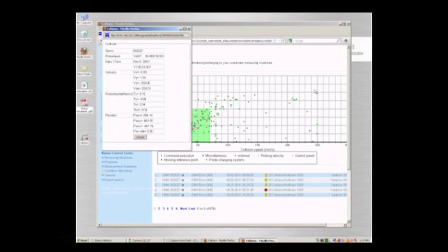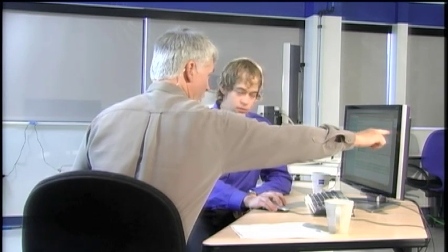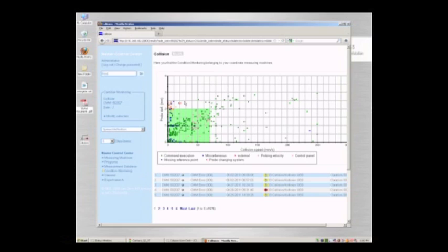What are we seeing here, the X and the Y axis? What we see here is actually a collision speed, so millimeters per second, on the x-axis. And then we see probe head or probe deflection, so how much did the probe actually bend. So the worst case would be really high speed, a whole lot of deflection. Exactly. Parts flying, right. Down in the green zone, this might be from joysticking and accidentally bumping a part, but it still causes a collision. It's still reported, it's still logged, but it's the full recovery of a machine.